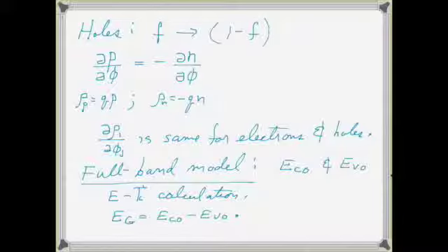So your band edges are now a function of position for site J. There'll be whatever there is with no potential, minus Q phi sub J, and same thing with the valence band edge. And so if we think about what's happening, you're going to have these regions where there's a lot of band bending.